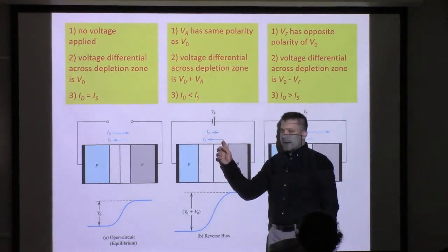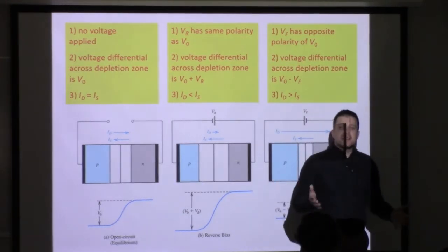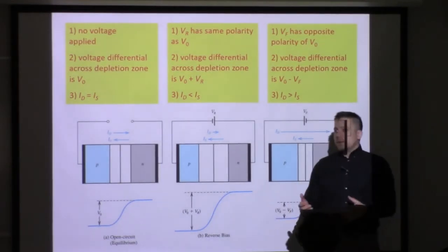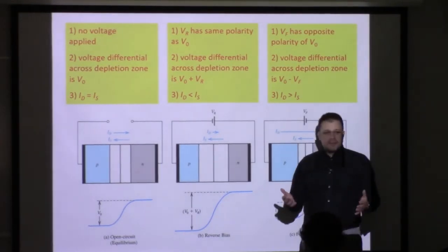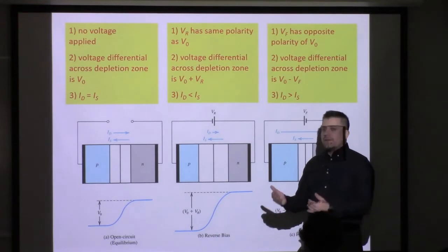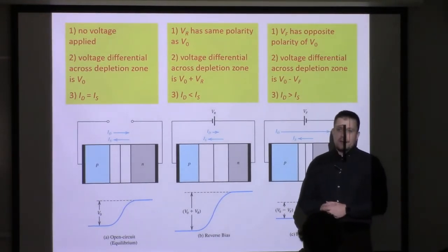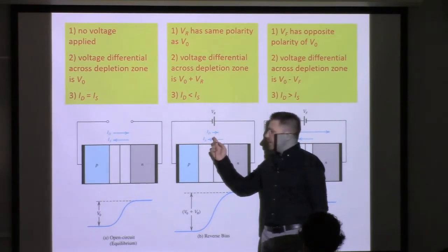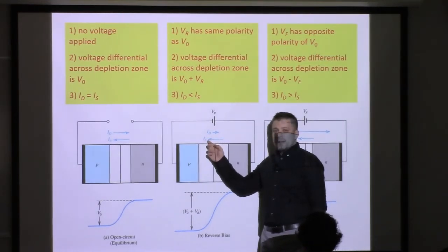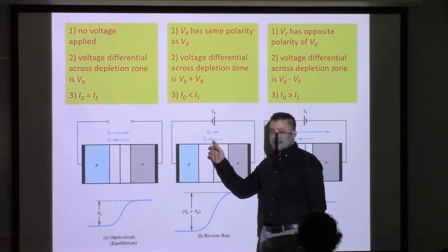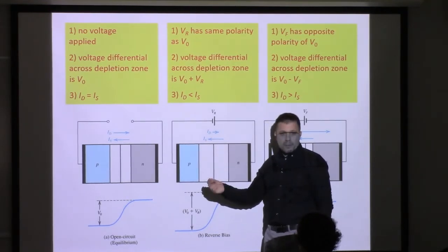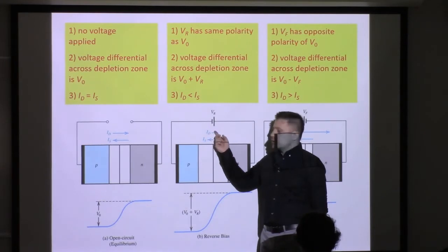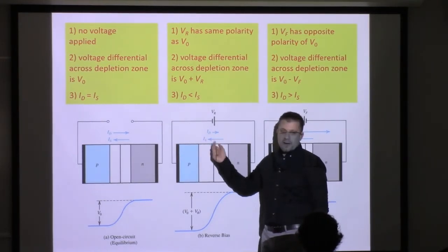So for the reverse bias case, as far as the ideal model is concerned, we think of that as blocking. But for those of you who have seen the diode in lab, it does conduct a very small reverse direction current, and that would be equal to IS minus ID. But again, there's only so big this can become because IS itself is very small. So if this is 1 nanoamp, even if you subtract 0 from it, you're still only left with 1 nanoamp.